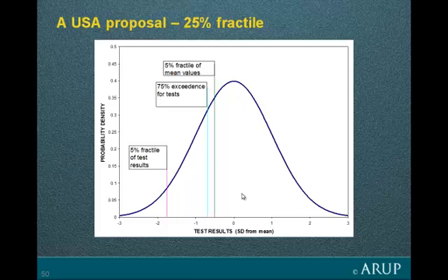American work looking at a similar problem has suggested that a good way of estimating what they call a conservatively assessed mean, rather similar thing, is to take a 75% exceedance value. In other words, 75% of your test results are better than what we would call characteristic value. That's quite a good guide. I think it's a useful guide to look at, but not a hard rule.